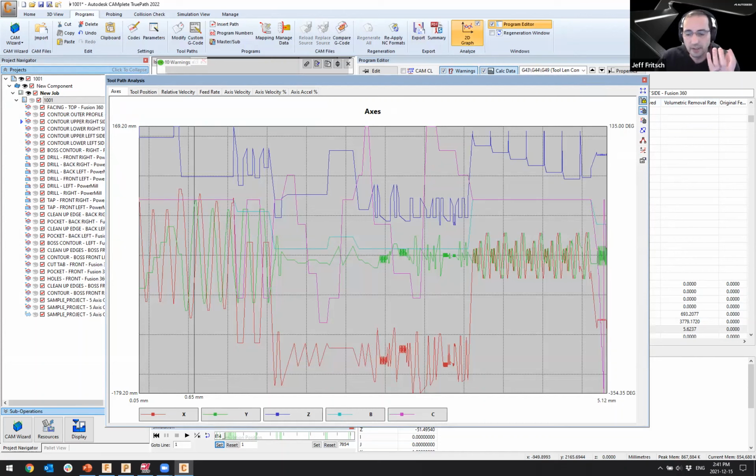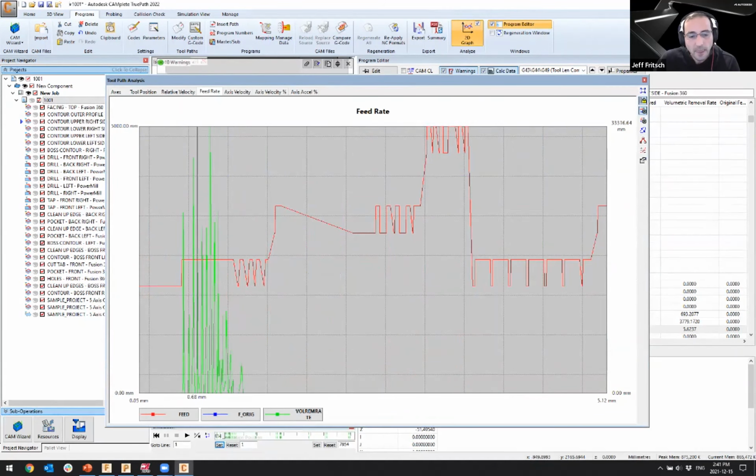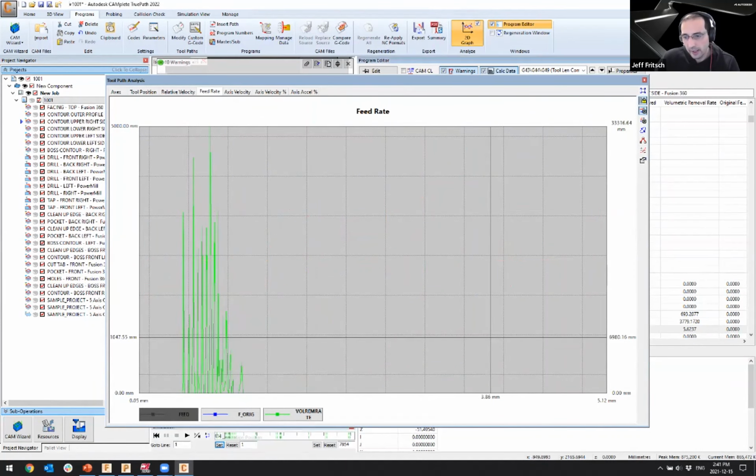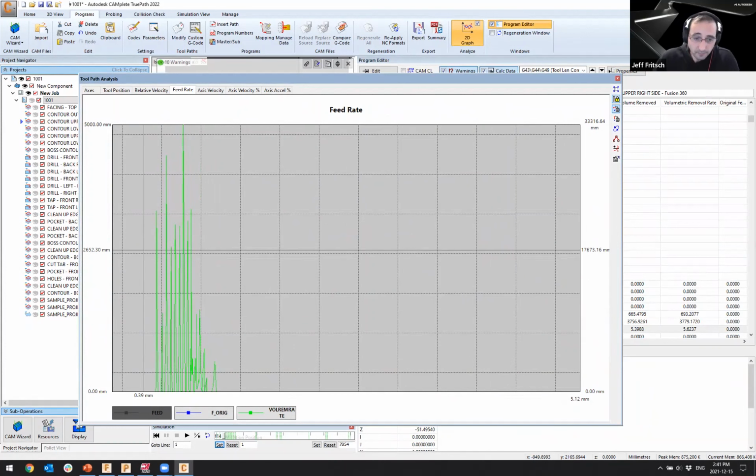that would typically be associated with 5-axis machines. So you've seen a lot of C-axis jerkiness when you get very close to the vertical position, one axis that accelerates very fast into a sharp corner, which axis of the trunnion, do you have a lot of reversal? All of those behaviors will be seen very clearly. But what I wanted to highlight there with that volumetric material removal rate, and basically how much material gets removed, is that now we can see the tool engagement into the material.